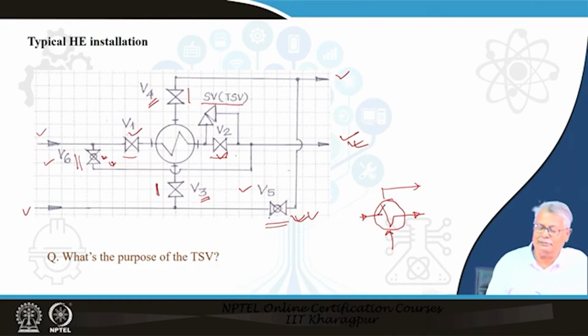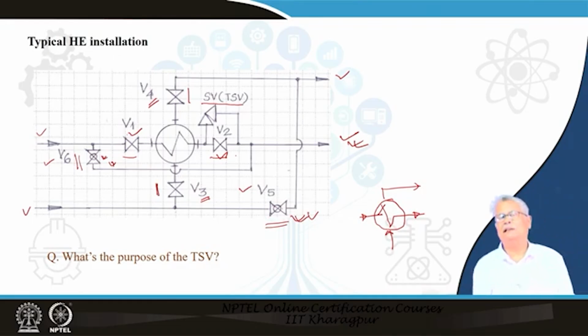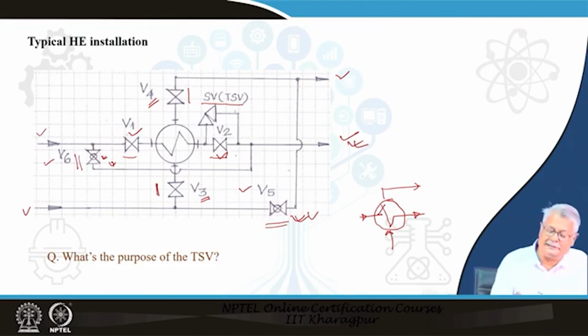A safety valve is basically to release overpressure. You will notice when it releases, the release is through this particular path. That means, if I have overpressure at this particular point, some amount of liquid will be flowing through the safety valve depending on its setting, and it will come here, and in the process it will get depressurized, or rather the pressure will get released. Now, let us see when this may happen.